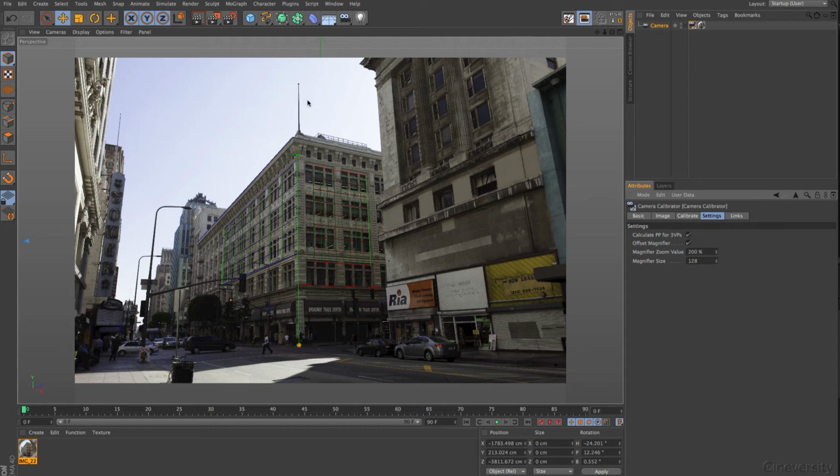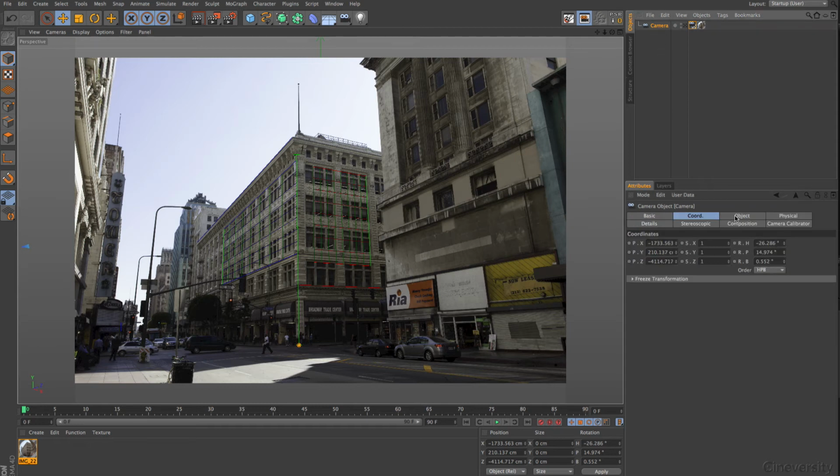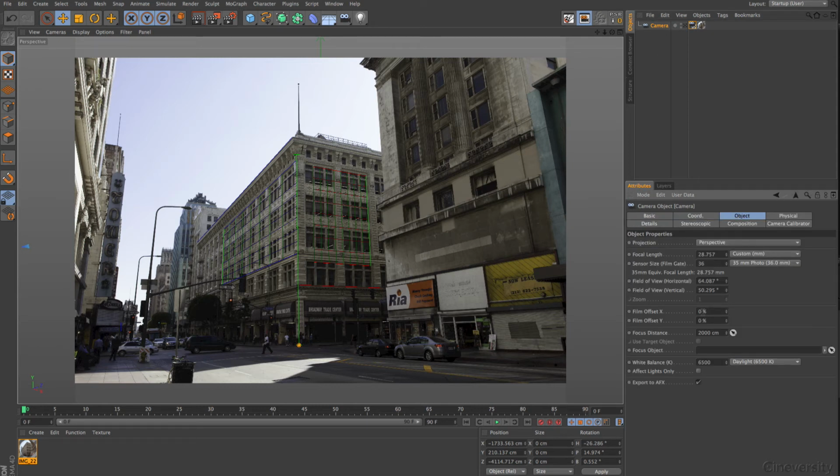You remember that? I talked about this. And of course, each building that is not parallel to it will have different vanishing points. Very important to know. So I would say normally don't use this. Now you will ask, why is it then on by default? Because sometimes when you go to the camera, you will find an offset even with a perfect image.